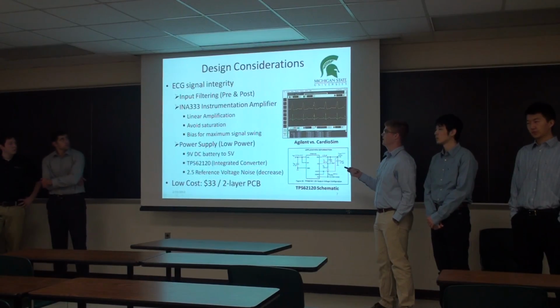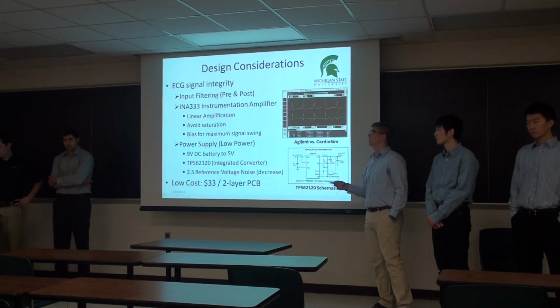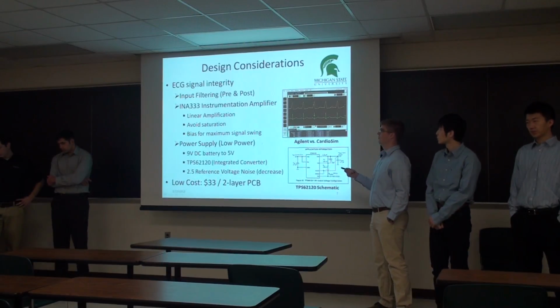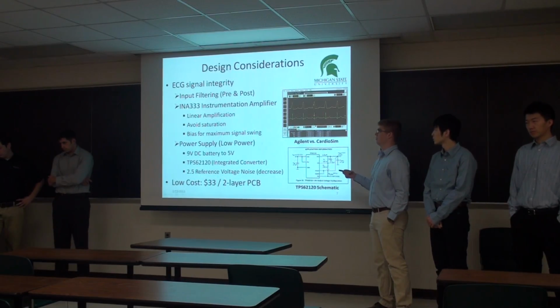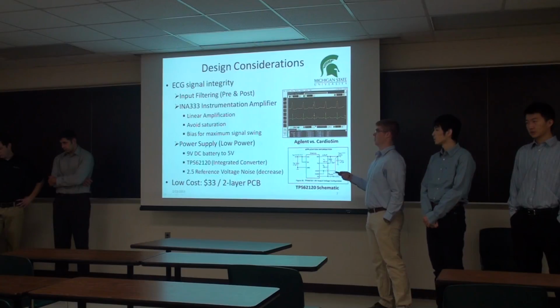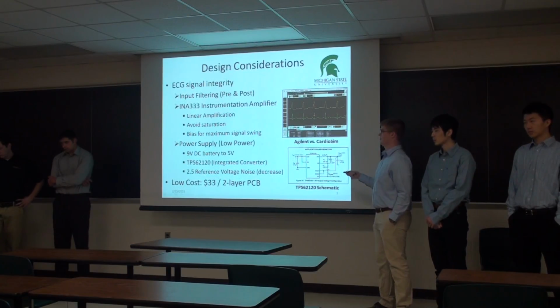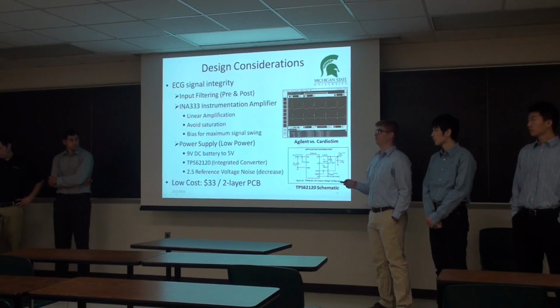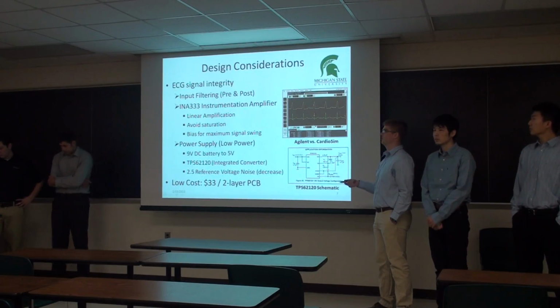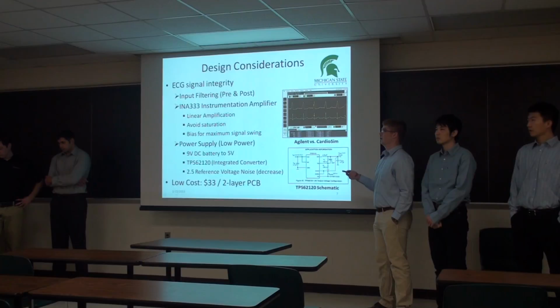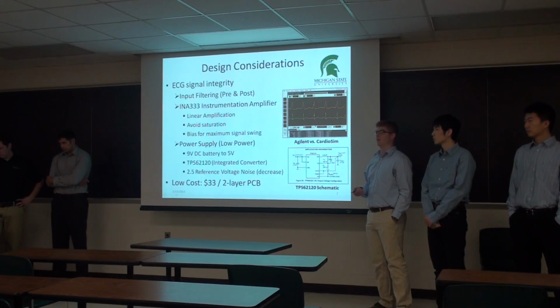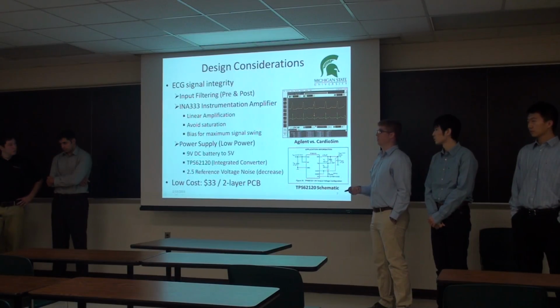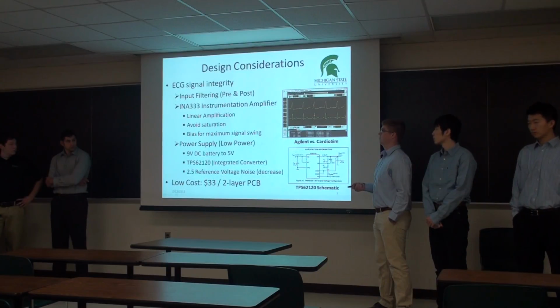The main causes that could give us bad signal integrity would be poor input filtering and also poor output filtering. What I mean by that is, in our design that Justin will touch on, we have RC networks on the inputs that have common mode and differential mode filtering. And then on our output, currently for our design, we have a simple inverting low pass filter to filter out high frequency noise.